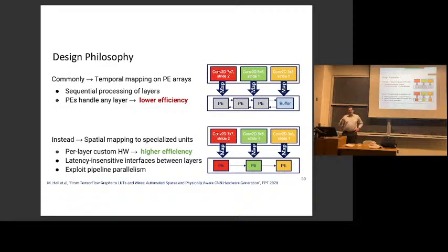So it's exploiting pipeline parallelism a lot. Each of these PEs is deeply pipelined with just regular registers. And then in between the PEs, we're basically pipelining between the layers with FIFOs and ready valid signaling, what's called a latency insensitive pipeline. So we're using 2 different streaming models: a simple one inside the PE, and this more flexible one where you can actually stall and you have FIFOs in between the PEs. Does that make sense? Is everybody with me so far? And if there are 50 layers in the neural network, you wind up with 50 different PEs, all implemented in the chip.